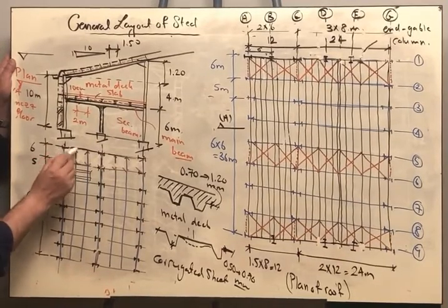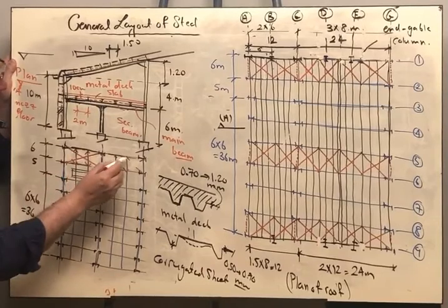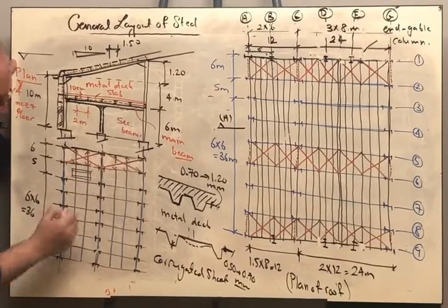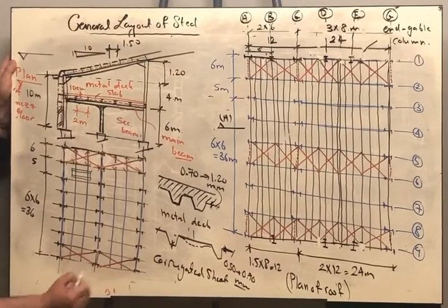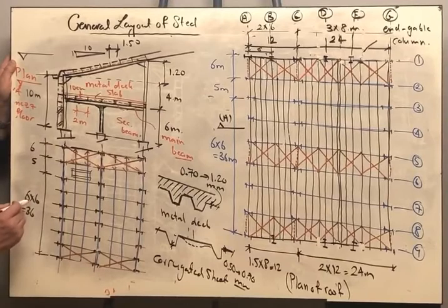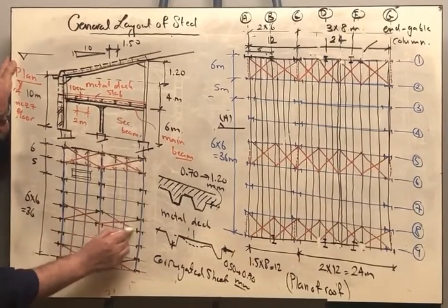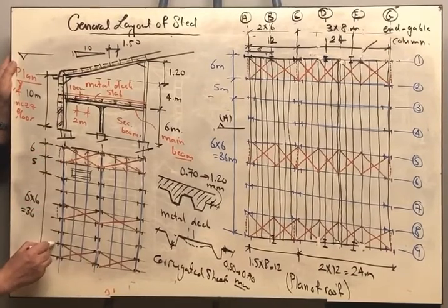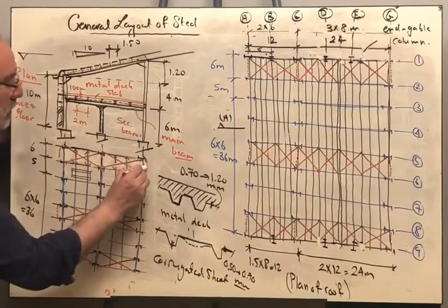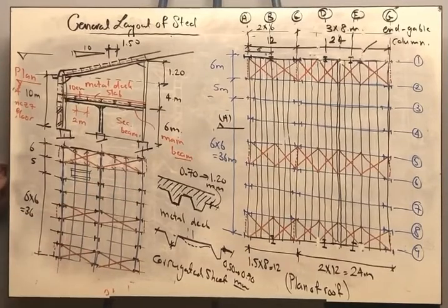We are having this is 6 meters and this is 6 meters. They are supposed to be the same. Then the bracing can be like this. Okay, and of course we said that we are having a bracing also in the middle. And associated with the horizontal bracing, there should be an indication for the vertical bracing. Again, this is just an indication. It doesn't matter whether you draw it on this side or on that side.